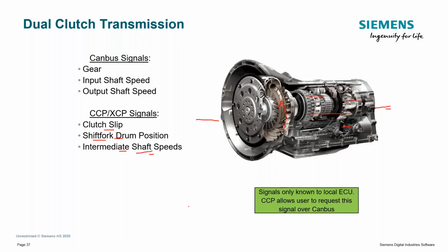So to do that, it's pretty simple. I'm going to draw a box because I realized I left the slide. I've got my SCADAS, and the SCADAS can only read CAN bus. So it expects a CAN signal, not a CCP signal. We have the vehicle over here, and so what we need in between, and they're very common devices, is a gateway device.